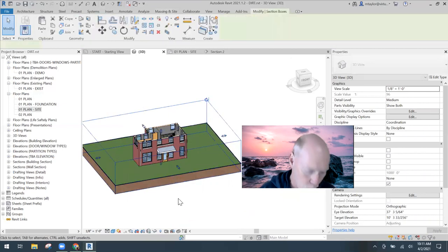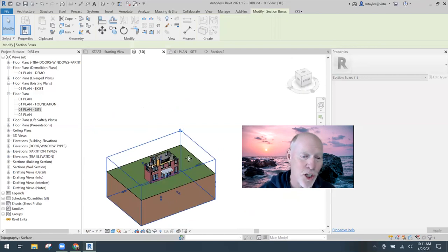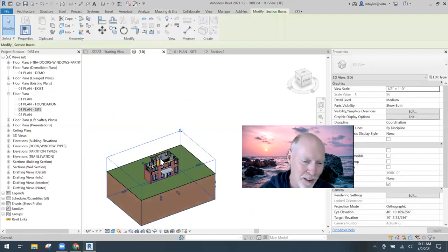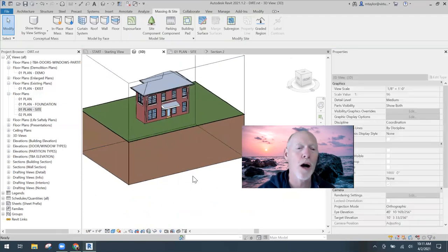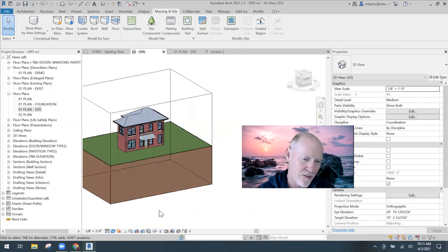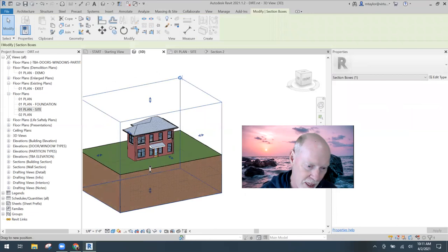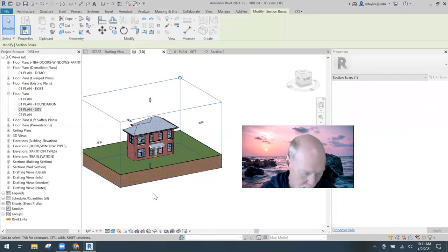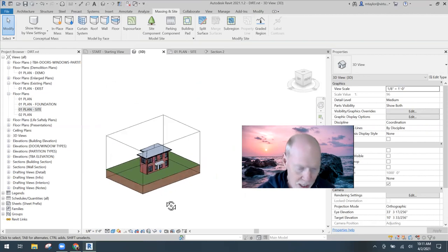And if I pull it down further, it adds a ton of dirt. I'm going to lift this back up so you can see my roof. Look at that. Look at all that dirt. Whoa, we got tons of dirt under our building. Okay, that's kind of silly looking, and it will draw people's attention to it. So you don't want it to be that deep of dirt, but give it some dirt, okay? Now we've got a flat topo surface.